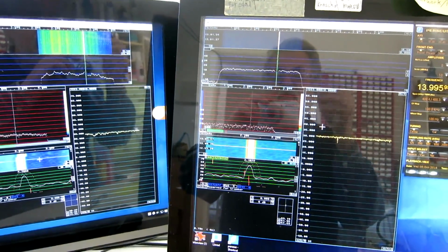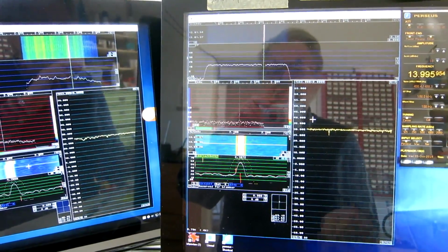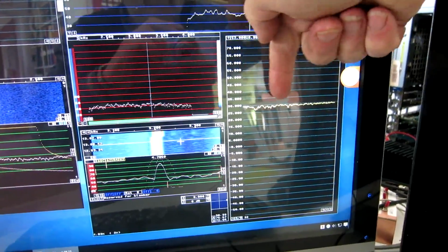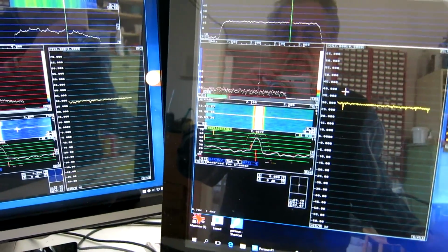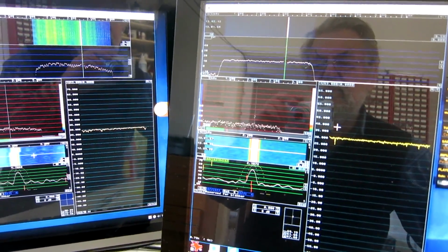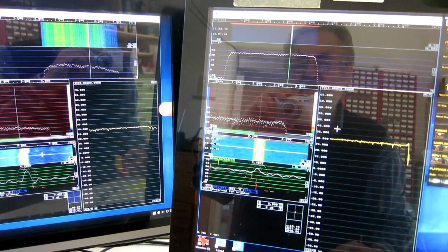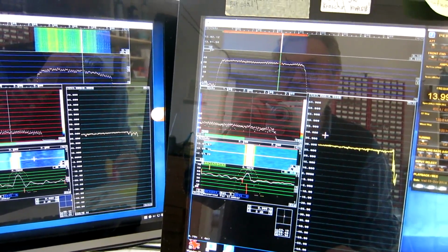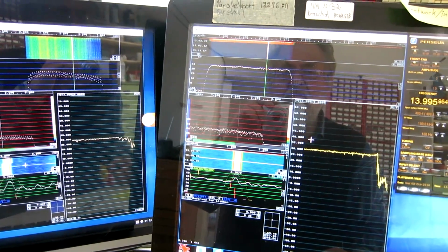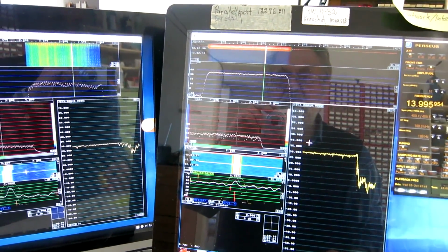At this point there are occasional interferences. You can see something here and something here. I increased the antenna signal by 3 decibels, and we can see problems in both radios. Severe problems occasionally in the Perseus because it's clipping.